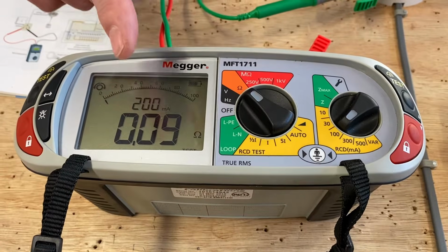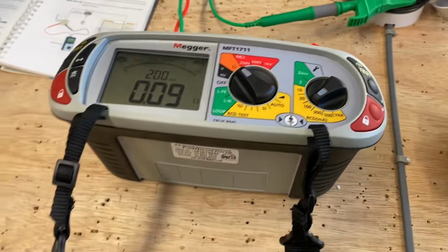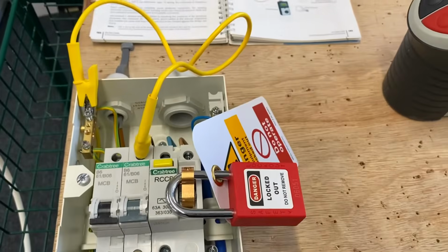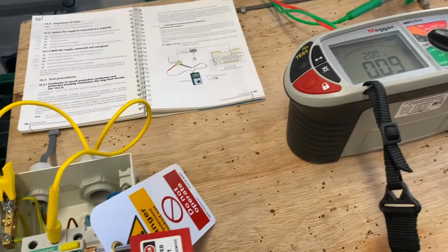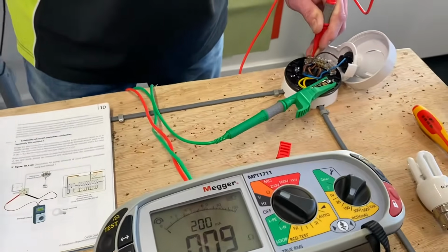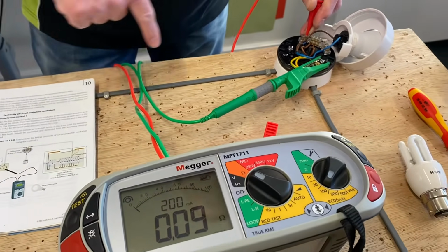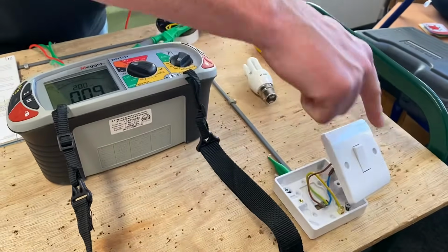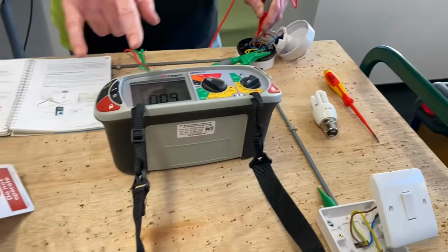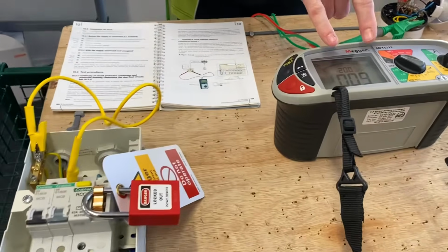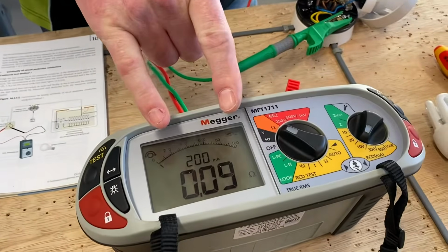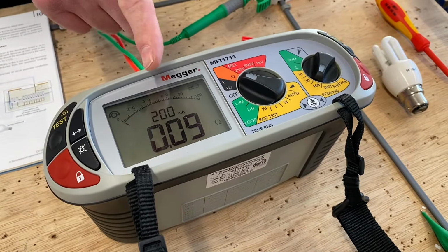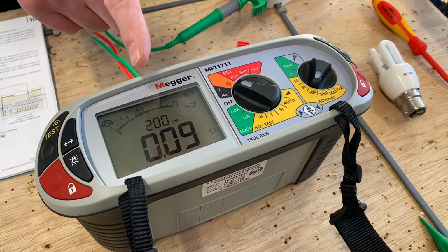So, in other words, if we just pull back slightly, we've got a cable from here. So the CPC from here comes to here, and by connecting, gets all the way back. So we have a completed circuit. So it will come CPC in, down to the switch, from the switch back and round as a complete loop, and we've measured that resistance as 0.09. We would record the highest value of reading, so we need to remember that one, but I said we were going to perform the polarity check at the same time.